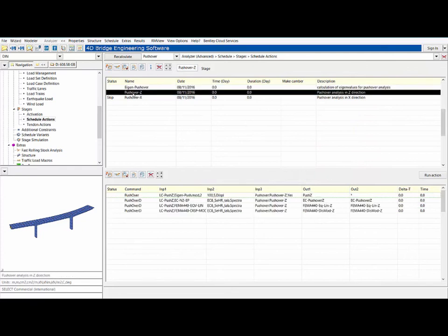And then we create another action for the pushover analysis. This action, as you see here, has pushover and pushover D. With pushover, we will calculate the capacity curve, and the pushover D action basically refers to calculating the demand. And because we are performing three different methods, I have created three different pushover D actions: one for the Eurocode, another for the FEMA 440 equivalent linearization, and the last one for FEMA 440 displacement modification.